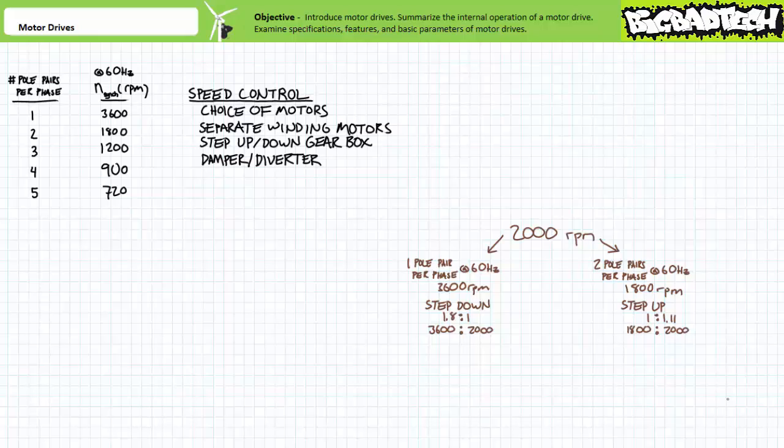Old school flow control methods for hopelessly outdated systems, believe it or not, ran a motor at full speed all the time and simply tightened down a damper or diverted flow elsewhere if less than full flow was required. Talk about wasted energy. This would be equivalent to driving to class with a gas pedal on the floor at all times and modulating your speed around every turn, stoplight, or school zone with regular and constant applications of the brake.